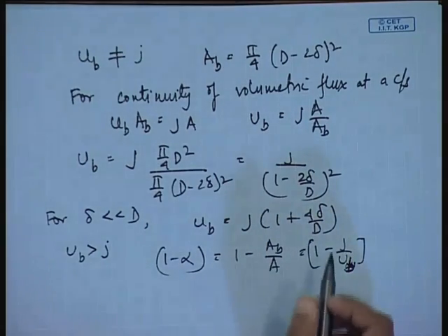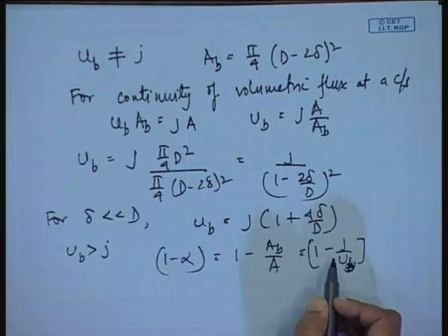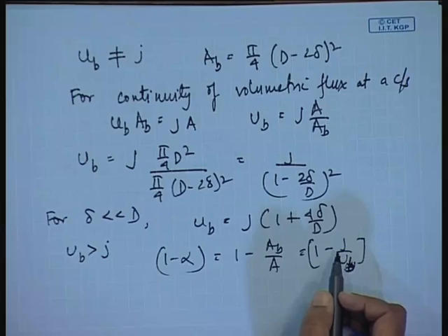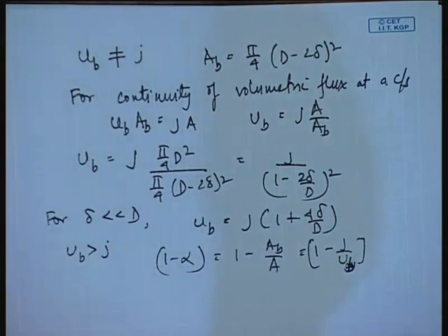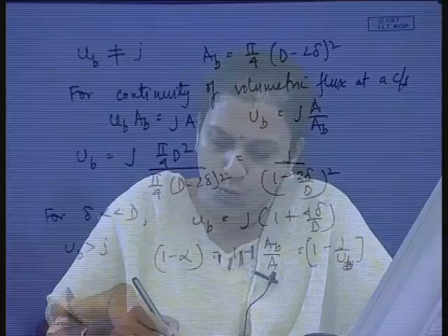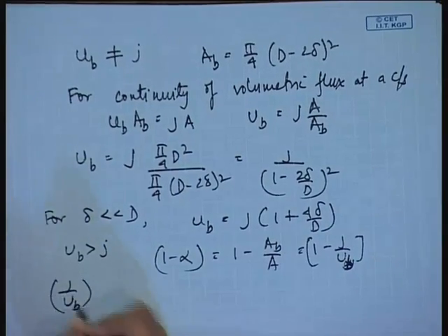So, we find from dimensional analysis, in the absence of effects due to gas viscosity and gas inertia, if we neglect these two things, then for bubbles which move independently, that means they are not falling into each other's wake, or in other words the liquid slugs are large enough, what are the important dimensionless parameters which govern this? One dimensionless parameter is definitely J by UB. Fine, because we have already got it. This is just the liquid velocity in the slug divided by the bubble velocity.